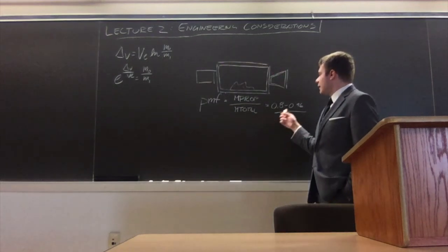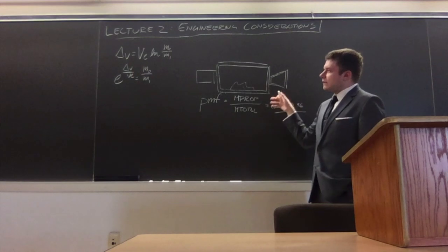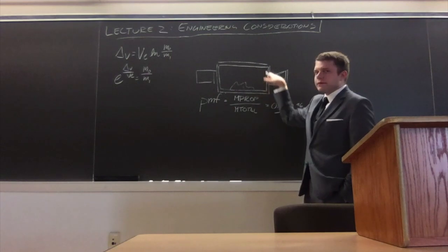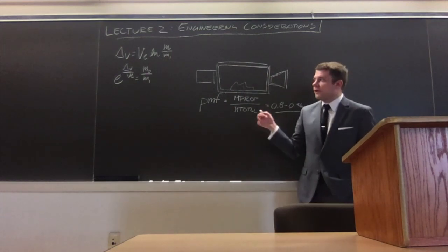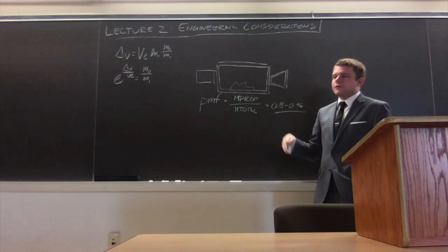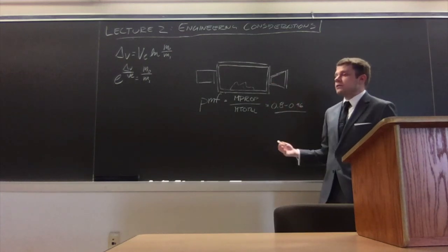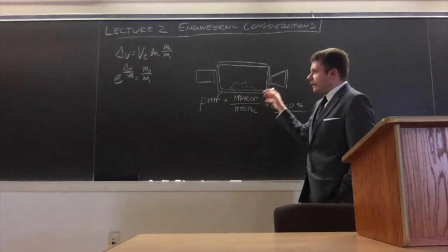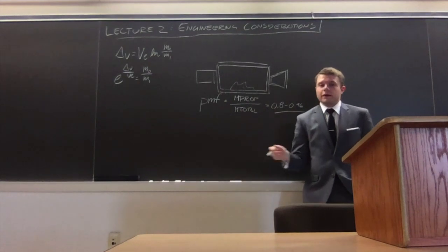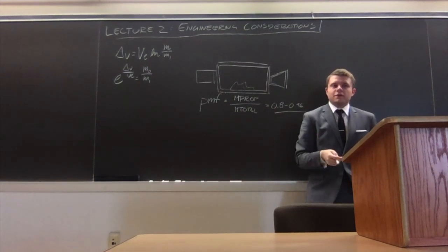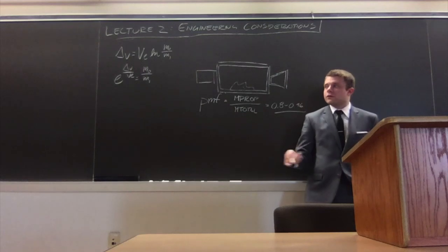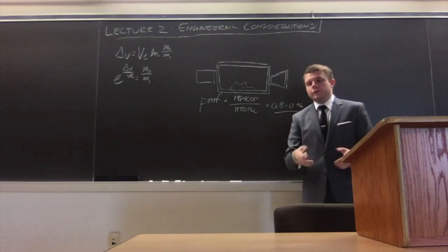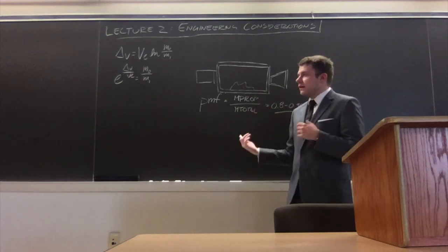Liquid rockets, you can get away with a higher propellant mass fraction because, in a sense, you're not just dealing with solid motors, I should say. With solid motors, the entire casing has to bear the thrust the engine produces, whereas with liquid motors, it's just the engine that has to deal with that. So you can get a much lighter tankage. You can basically have almost gossamer thin propellant tanks. And there are rockets, even in the world today, that still use very, very thin and lightweight propellant tanks. Those are called balloon tanks. The Centaur upper stage that's used to this day, which burns liquid oxygen and liquid hydrogen, uses a propellant tank of that nature. It's basically just a large stainless steel balloon. It's pressure stabilized. If you take out the pressure, the whole thing collapses.